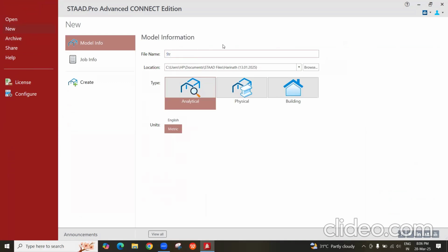My doubt is where we can use this analysis method. For example, the vehicle load for the EOT overhead crane, for gantry girders or something like that, there we can use the vehicle load method, moving loads. So where can we use this practically? In seismic analysis, why are we finding this? We are finding base shear and time periods, right? And that's why here also we are getting maximum deflection. With this we can study any structure.